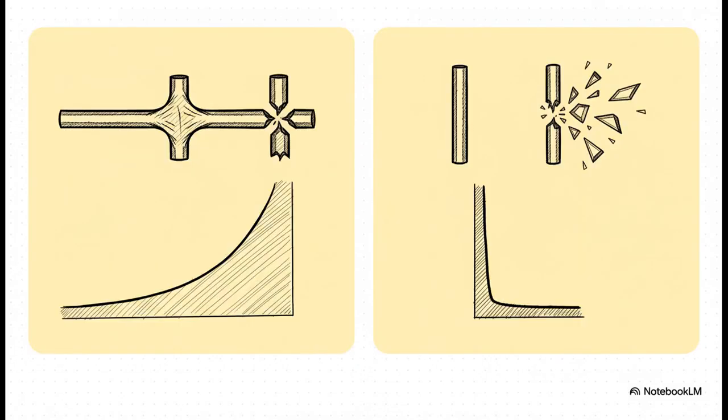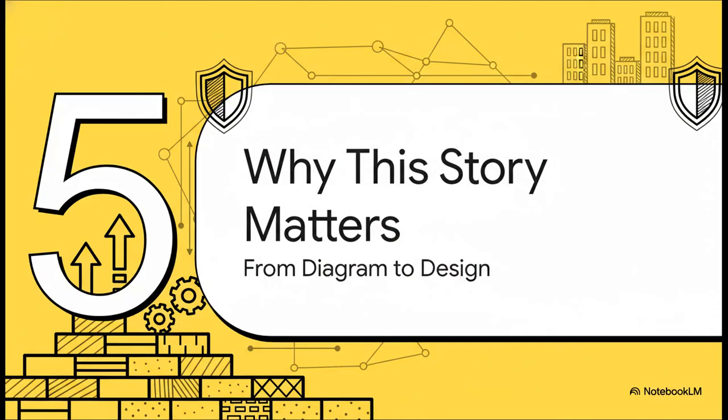So here's the bottom line. Ductile materials, like steel, stretch a lot. They give you visible signs like that necking we talked about, that things are about to go wrong. Brittle materials, like glass or a piece of chalk, fail without any heads up. Now you can probably guess why engineers usually prefer material that screams a little before it completely breaks. Okay, let's bring this all home. Why does reading this story matter so much? It matters because understanding it is how we build a safe, reliable world around us.